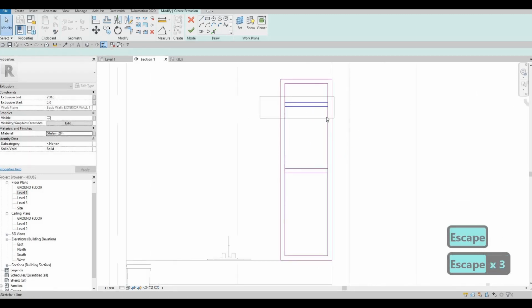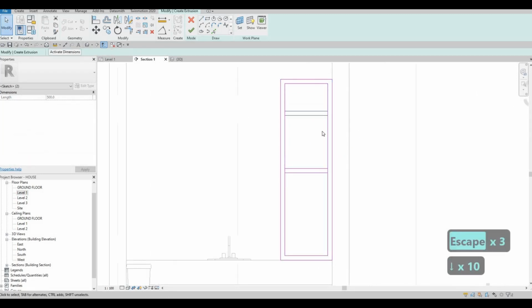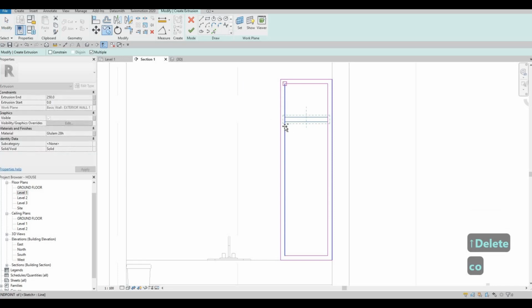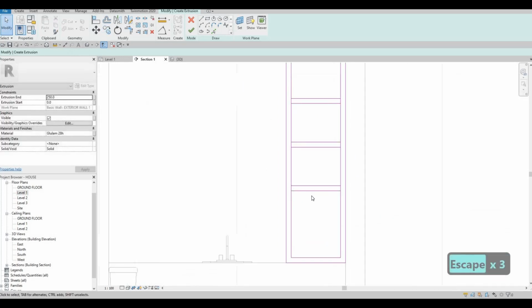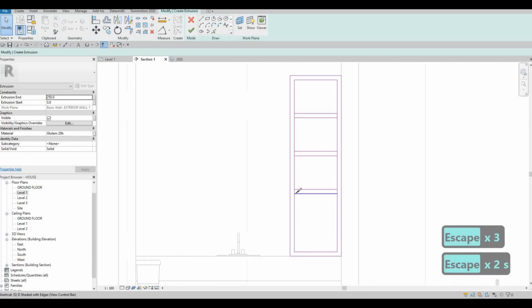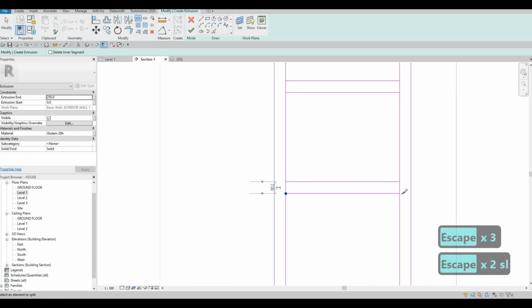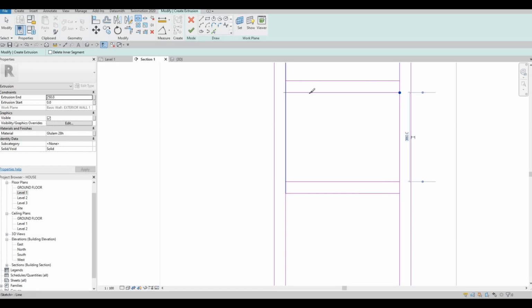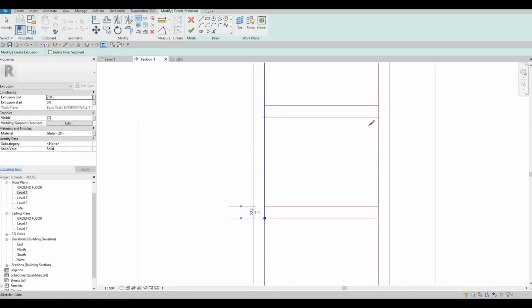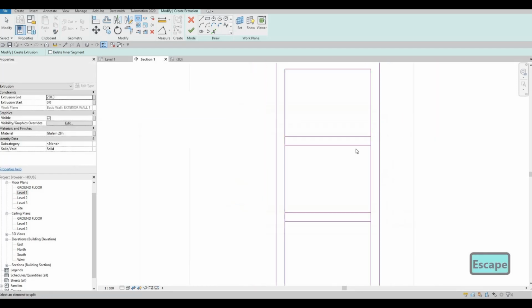And then I think it's better to just move it like this and then copy so that we have proper spacing, similar, and then make the last one bigger. SL, you can select one side to be sliced, and what you can do is TR, trim and extend, so it's faster now.